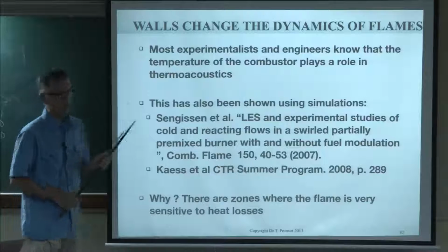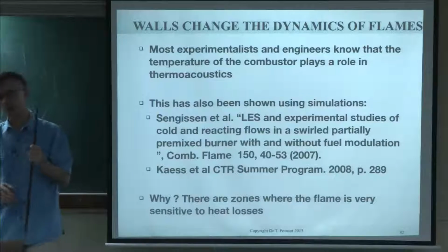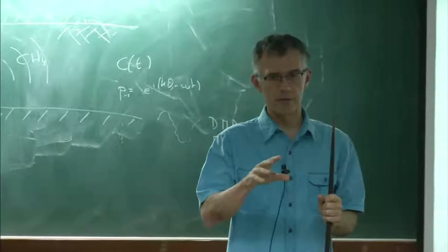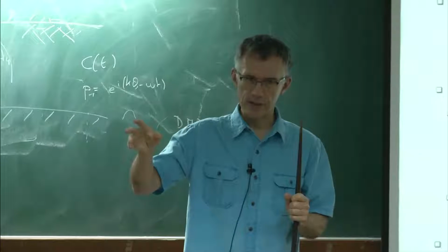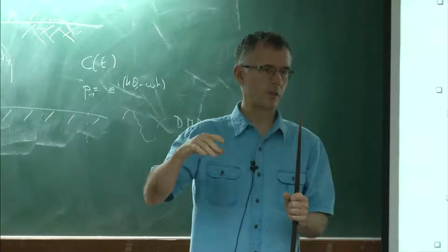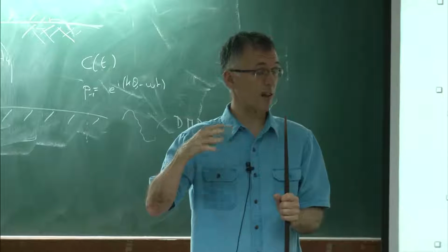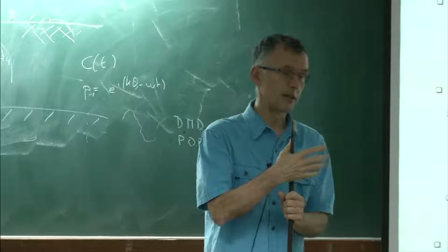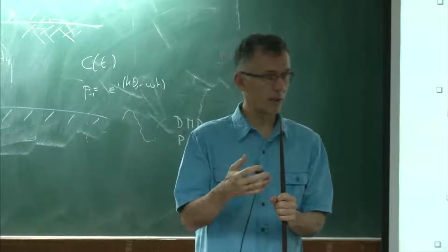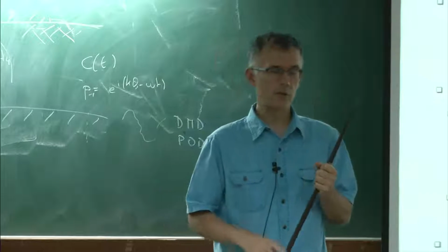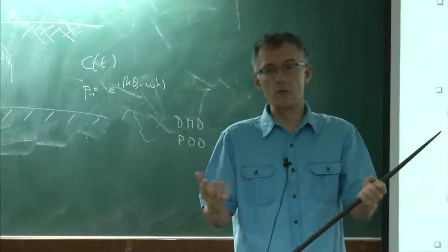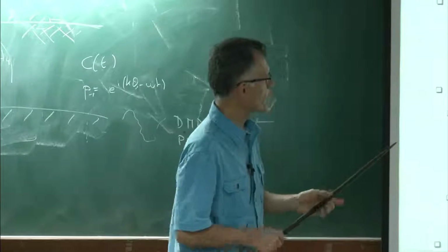The people who do experiments in combustion instabilities, all of them will tell you when I start my burner, it's doing something, and then I wait, and it's doing something else. This happens in domestic burners, it even happens in an engine. We talked about hooting 2 days ago, that's the same thing. When an engine is cold, some things may happen. So it really means that what is changing is the wall temperatures. So the wall temperatures play a role.